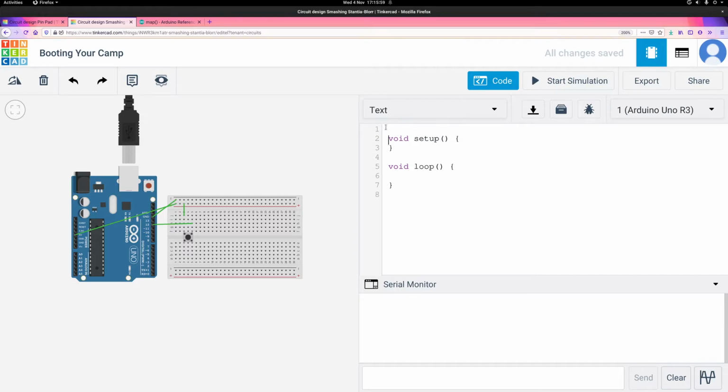Wonderful. So I'll start with a line that just says our pin number. So we'll have our constant integer. This will be our button pin, and that's connected to pin number 12. Stellar. And then we want to set this pin to be an input. So last time, you remember we did pin mode. So we had pin mode, then we had the pin itself, which was the button pin. And before we had output, remember, because we were driving an LED. But this time we want to read a value.